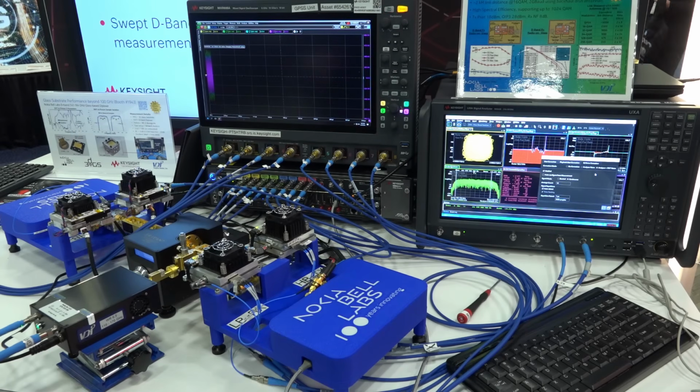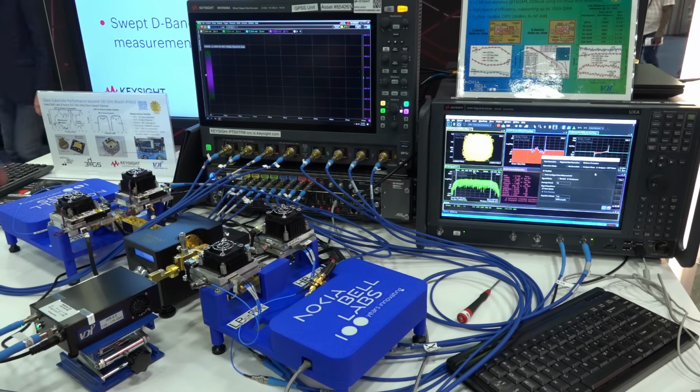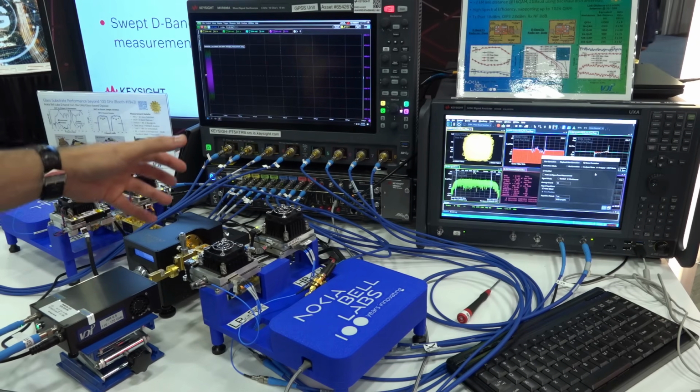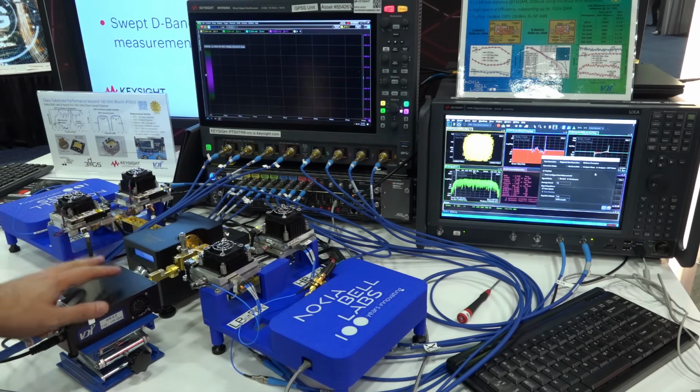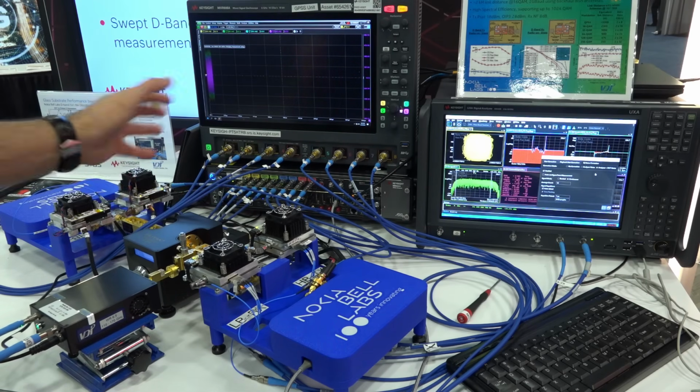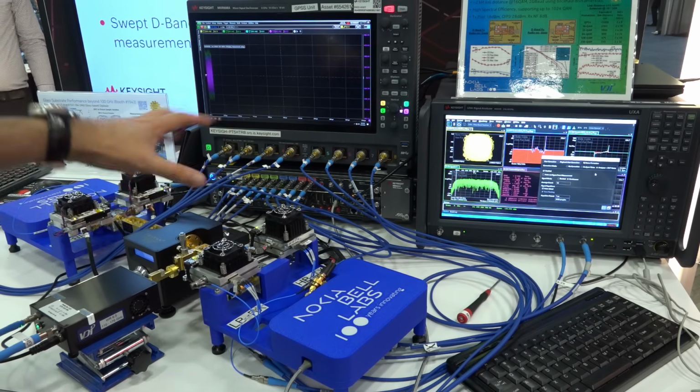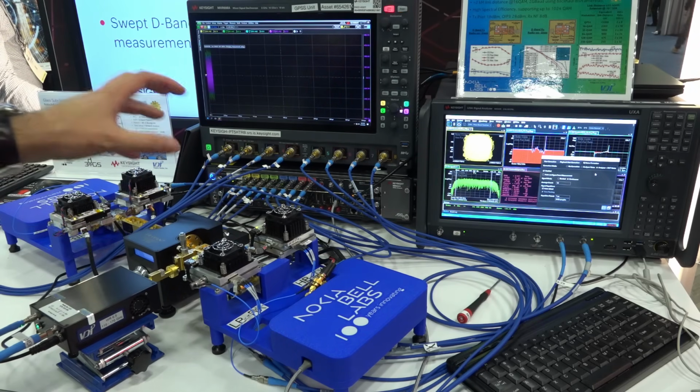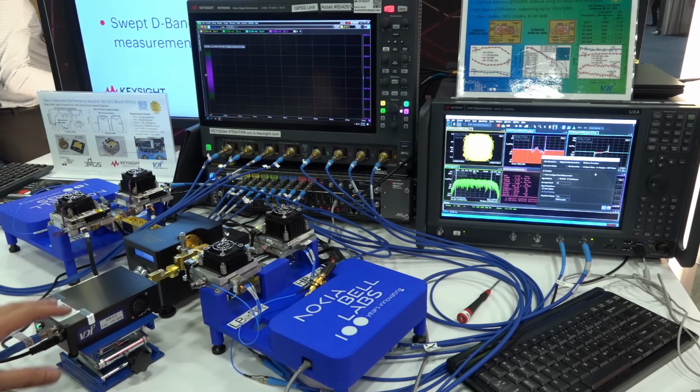And here now we have a complete D-band characterization system running live. There's actually a lot going on in the setup, because we're simultaneously capturing a D-band signal from these radios at RF, and we're also capturing it after down conversion at baseband through the equivalent receivers. Because there are so many things going on, you have to make sure that you capture all of these measurements simultaneously.